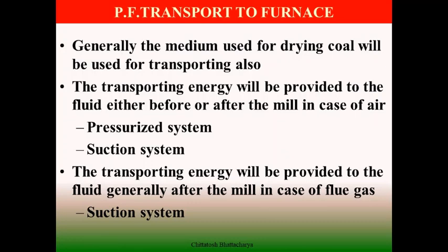So hot air supply is done in such a way that air is sufficient to dry the coal, at the same time there is no sufficient air to create a fuel-air rich condition, and there may be a mill fire. Besides that, we have to see the total coal-air mixture which is passing from the milling system through the coal carrier pipe and going towards the burner.